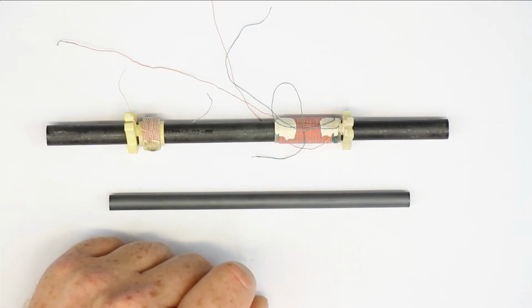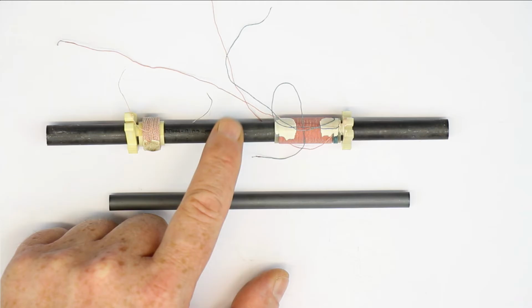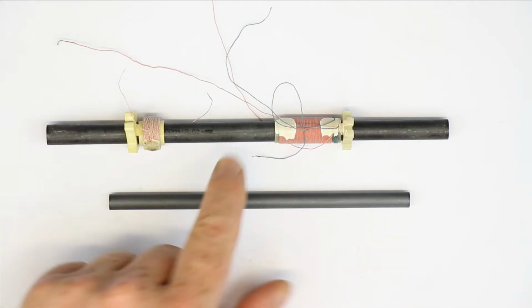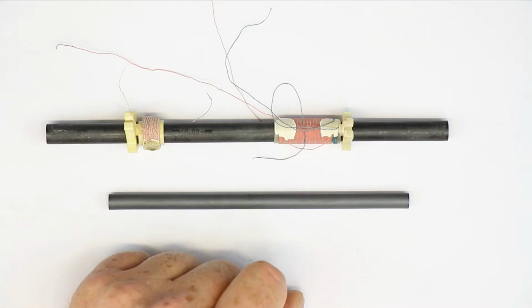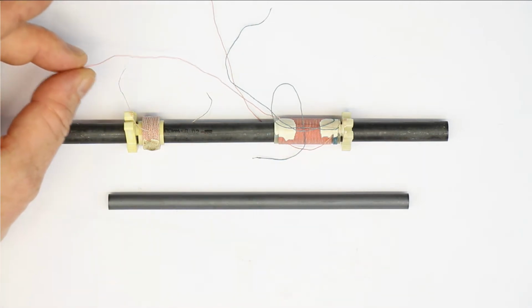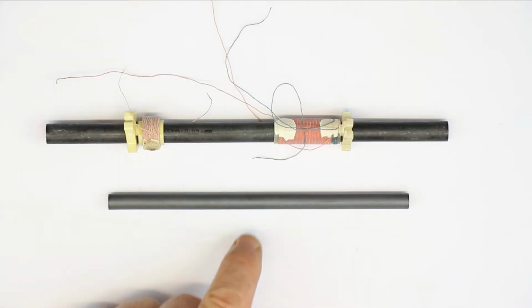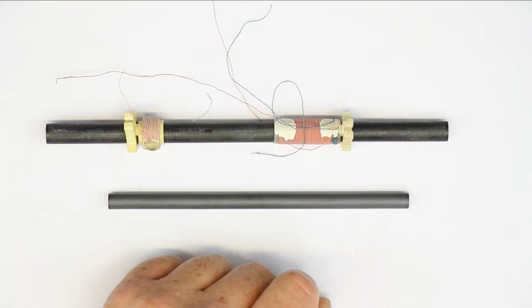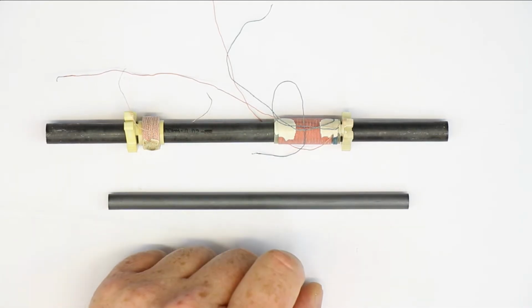But of course there are also one or more downsides to the concept of using ferrite materials. One of them is that ferrite materials are not suitable for very high frequency. We will discuss this in a minute. The second is, of course, you always get losses in the ferrite material. And the third is that the kind of wire that you use when you go to higher frequency, the Litz wire, which is normally used for long and medium wave reception, becomes less and less suitable when you go to frequencies above 1 megahertz.